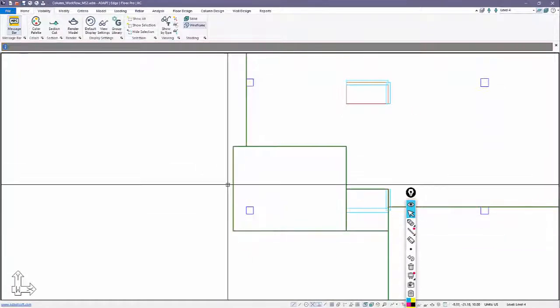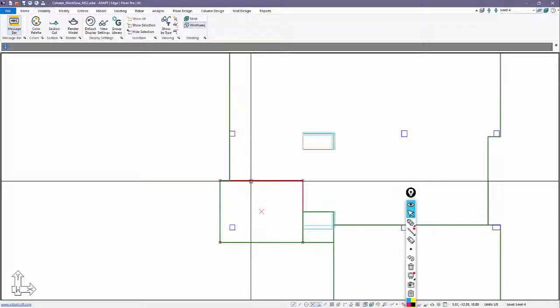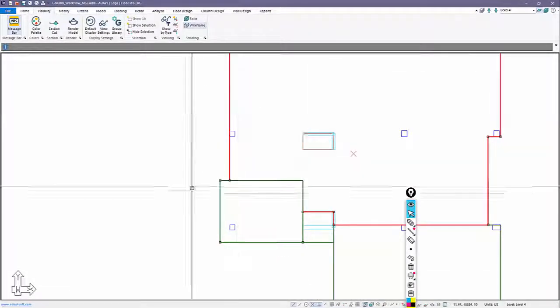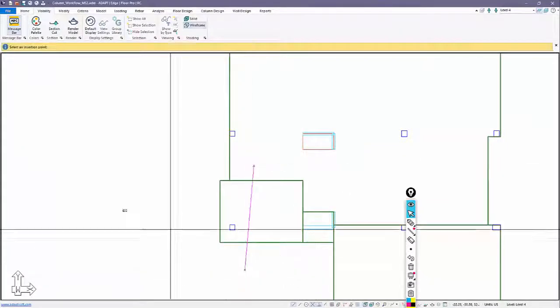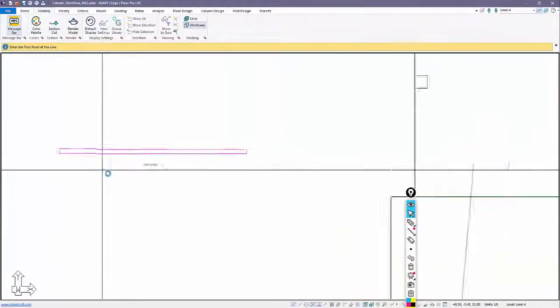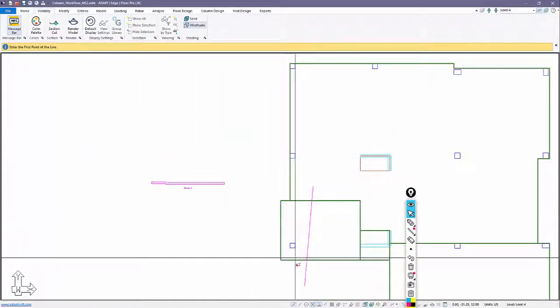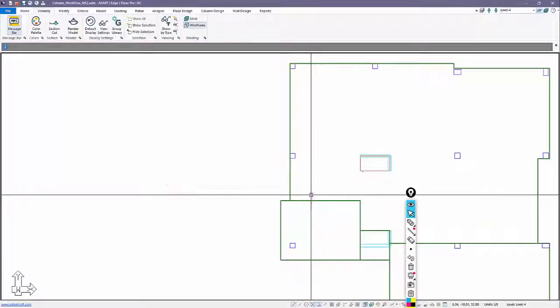So we've nested one slab on top of the other. We still are going to have an offset because this slab that's offset is actually contained within this larger slab that now encompasses it. So if we make a section cut through here, we still have the geometry that we want. It's just that now, in terms of column design, the program recognizes that it is touching a slab that is no longer offset. This is, again, the workaround.